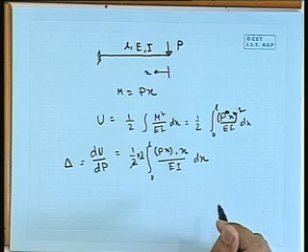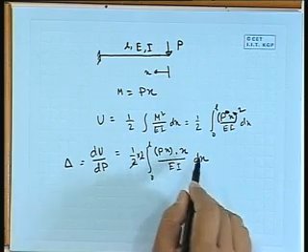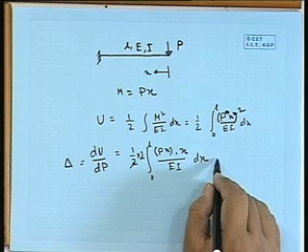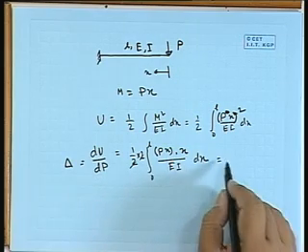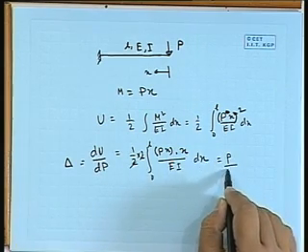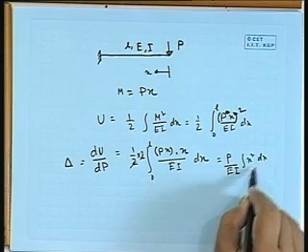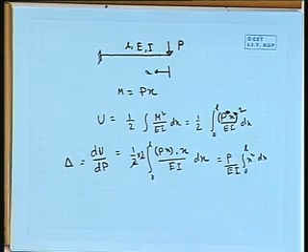Now, if that is the expression, it is px square divided by EI into dx. So, if we take out p and EI, it is basically the integral of dx from 0 to L. The integral from 0 to L of x square dx will be x cube by 3, and if you put the limit it will be L cube by 3, the other part 0 will be cancelled.